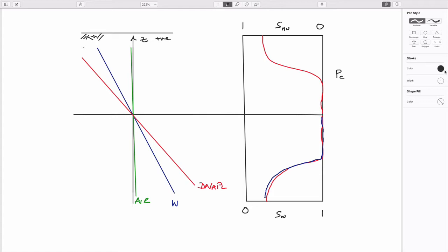And so when we talk about these two systems, they're no different from each other. I guess the top one, the other curve, I'll draw as green because it's an amalgamation between the red and green. And the point for doing this is that this capillary pressure merely scales with elevation. So capillary pressure would be equal to the elevation multiplied by the difference in the densities of the fluids, or the unit weights. For this one it would be the difference between non-wetting minus the wetting.